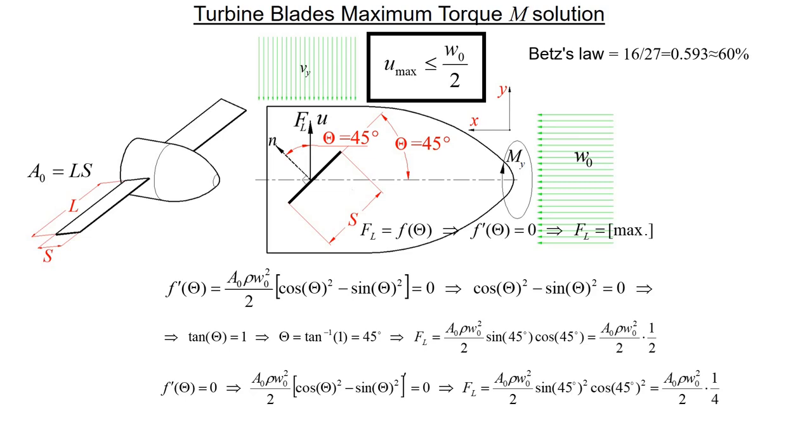In my theory, 25% of the kinetic energy of the wind, or 50% of wind velocity, can be converted into useful rotation velocity U max. The difference between Betz's and my theory is that Betz's limit is based on an open disk actuator. It means a hypothetical turbine without any geometry description, curvature, maximum blade number, angle of attack value, or info on the surface area of a blade.